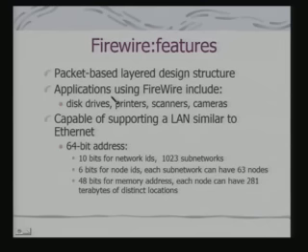Applications include disk drives, printers, scanners, cameras, and various other things which can be connected via IEEE 1394. It is capable of supporting a LAN similar to Ethernet, but of a limited variety over a limited distance. It has a 64-bit address.